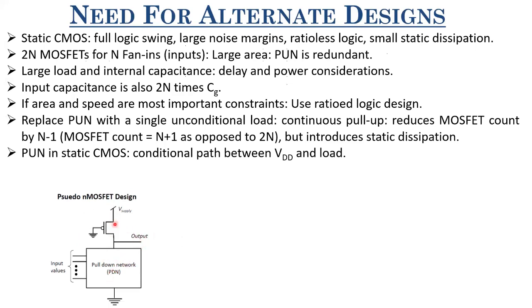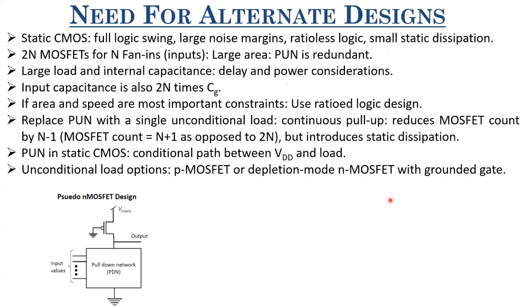Now, what are the options for this unconditional load? One is this PMOS with a grounded gate. Remember the discussion on inverters? We also have the depletion mode NMOSFET with grounded gate as one option. That is what we use for inverter design. Here also we can use it.